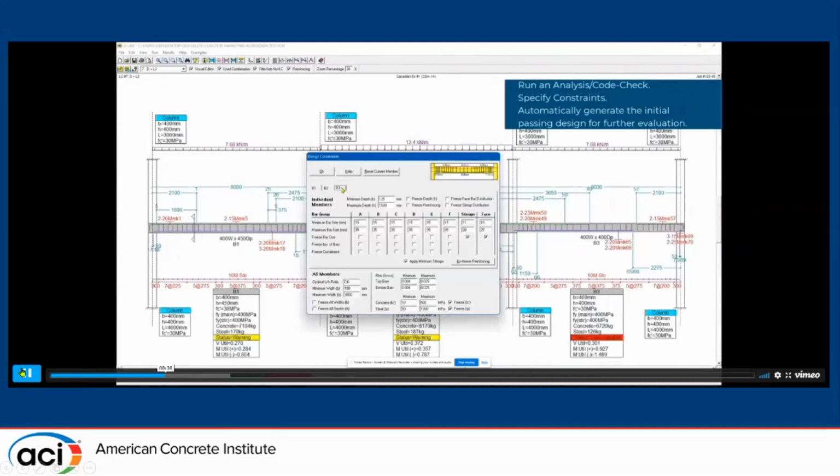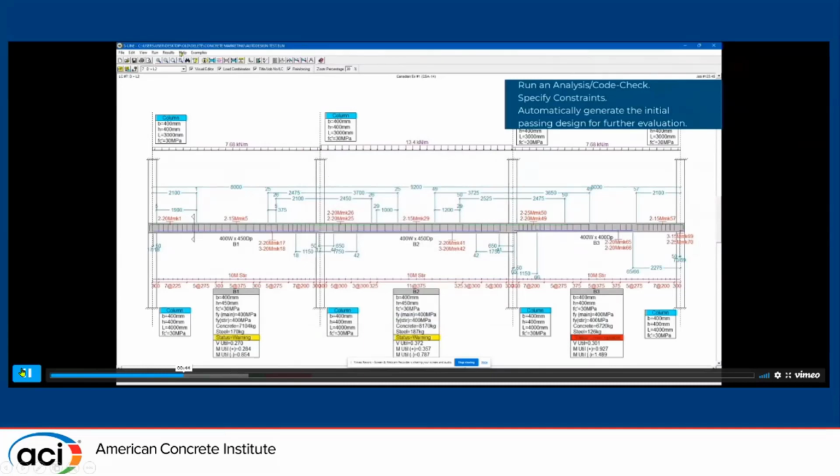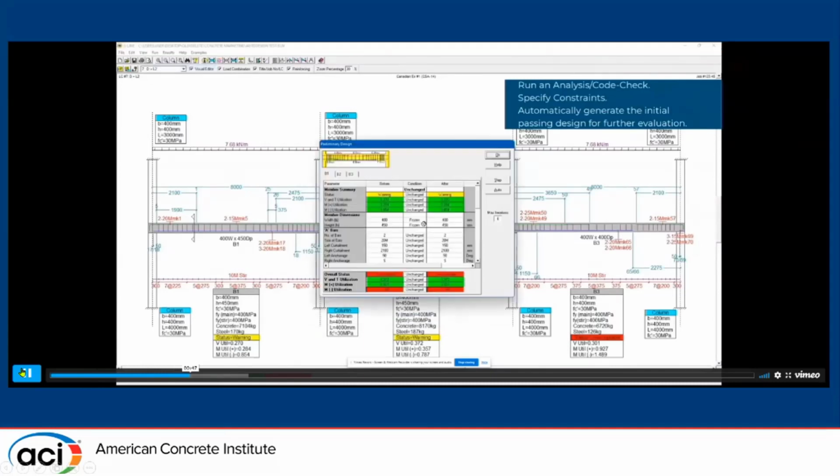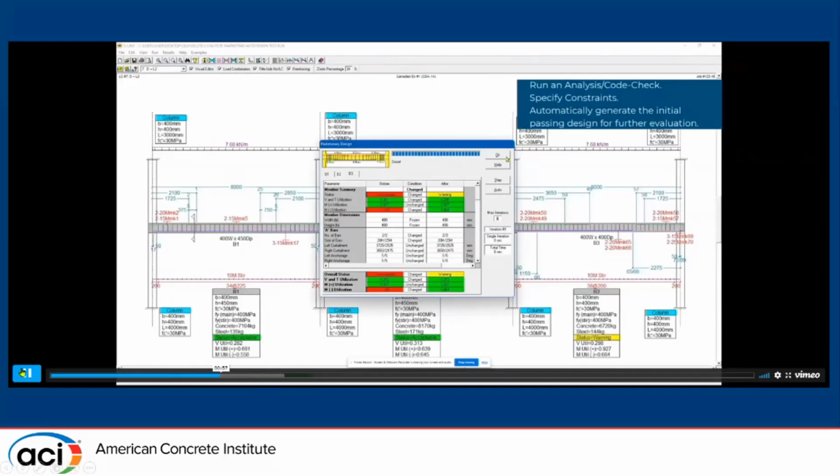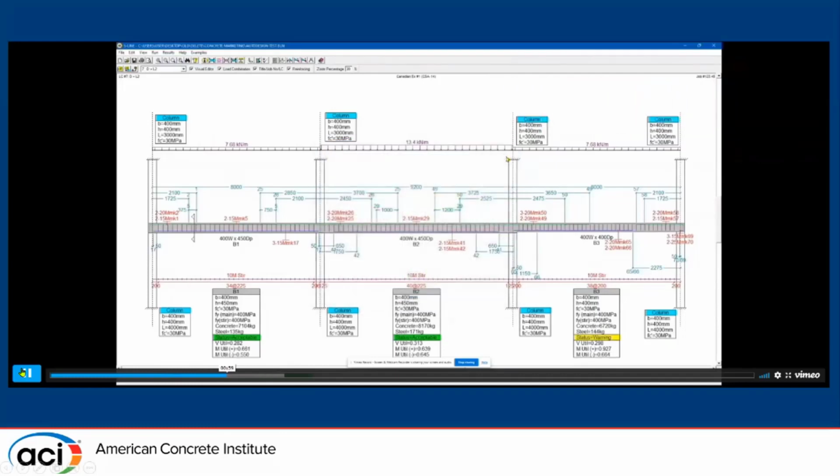They do this whole modeling program for you. You can go in there, choose your rebar, and they will do GFRP or steel so you can compare. If you have this modeled and your contractor comes to you and says, no, I want GFRP instead of steel, you can go back into your model, choose GFRP, rerun your model, and now you have your solution.